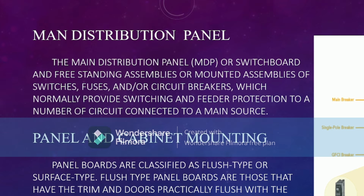Panel boards are classified as flush type or surface type. Flush type panel boards are those that have the trim and doors practically flush with the finished surface of the wall. Surface type panels project into the room, the cabinets being fastened to walls or columns. Also used in industrial plants.